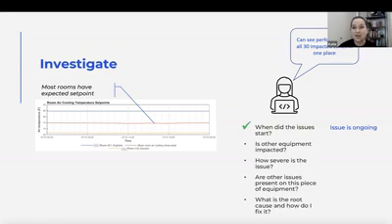And because we have a platform that's built to pull in data and create relationships between different pieces of equipment, you could look at things systematically. We understand that this air handler serves 30 zones. We know what those zones are. We have all the data on those zones in one graph. So we can look at this and say, okay, I know in this building, they have these thermostat sliders on the walls. I don't know how many of you have those on your campus, but where you can adjust your set point plus or minus 3 degrees from that base set point.